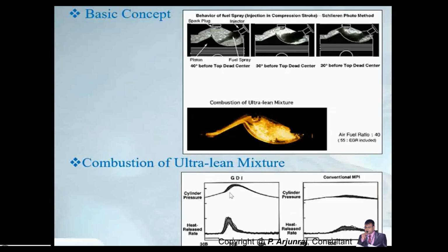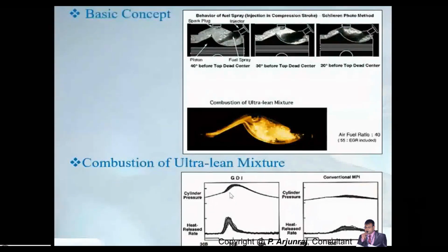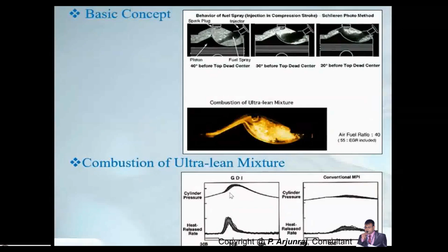So we have seen the stages of combustion in the case of an SI engine, where you have the ignition. Once the ignition starts, you get the combustion. When doing the combustion, the pressure builds up. When you're over advancing the ignition, you get abnormal combustion. When you're going for a retarded one, you get reduced power, torque, etc. So you're going for a normal combustion. Even when you're going for a normal combustion, your pressure builds up, and you will not get a knocking sound.